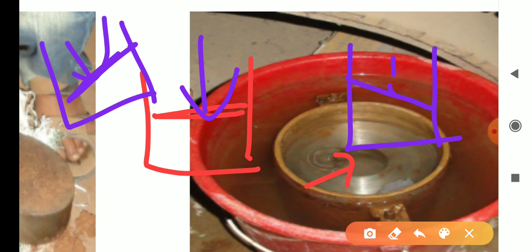So in that case we have to conduct the CBR test and find the percentage. Here the worst condition is the rainy season. That means the soaked condition value we have to consider for the design of flexible pavement.